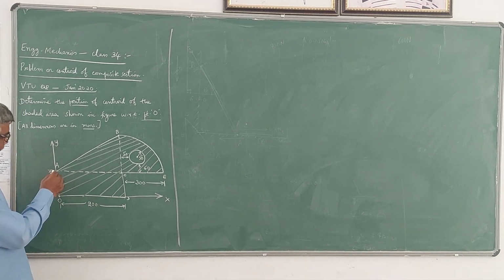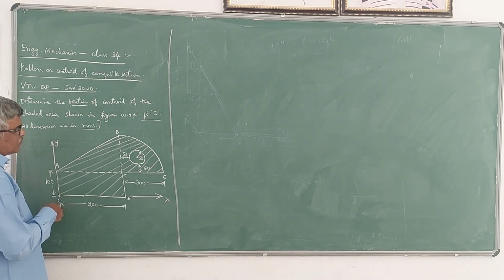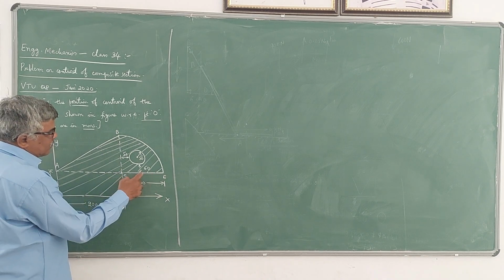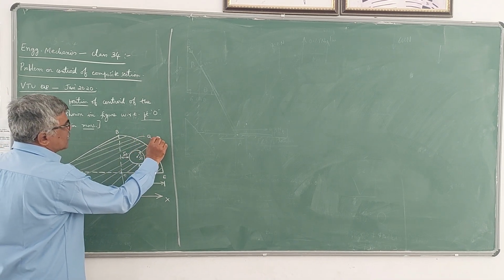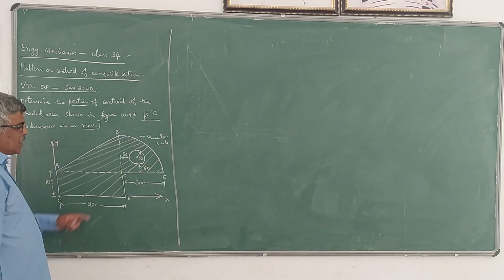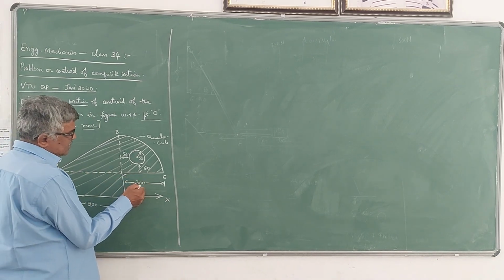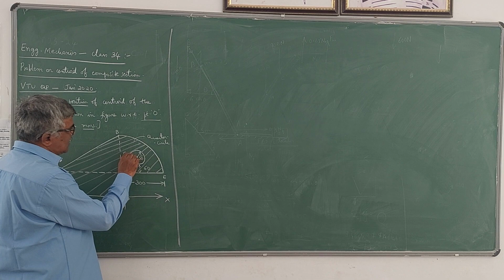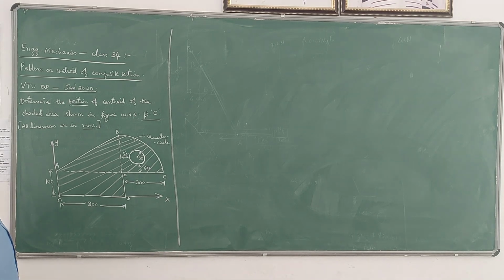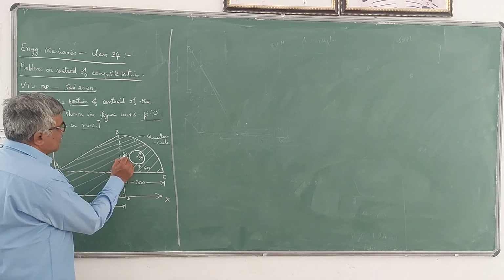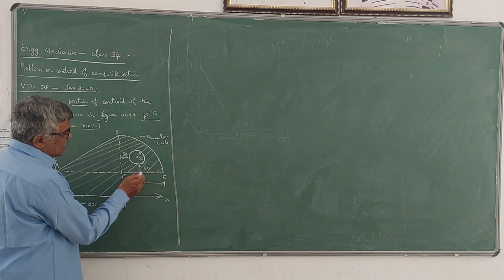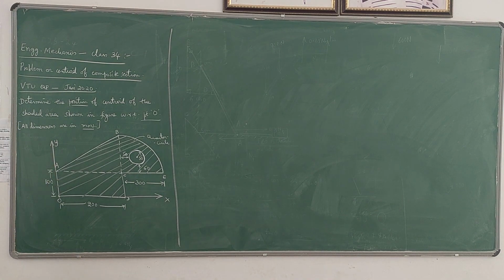sections. So one rectangle is there of dimension 200 by 100. One triangle is there of base 200 mm and height of course 300 because it's a quarter circle. It's a quarter circle. So that radius itself is the height of the triangle now. So 300 mm and quarter circle of radius 300 mm and in that there is a circular portion cut from the lamina. Cutout portion is there of radius 50 mm. Of course, it is placed at a distance of 50 mm from this rectangle edge and 60 mm from this edge. So this is how the figure is given.